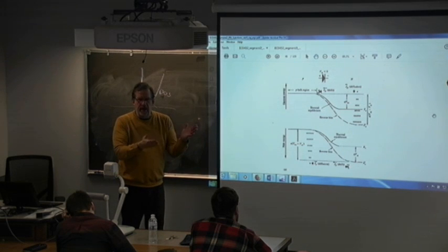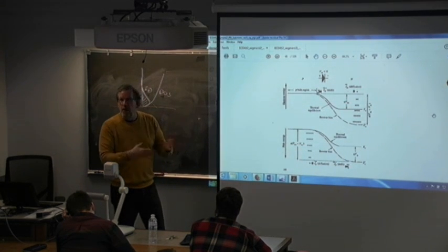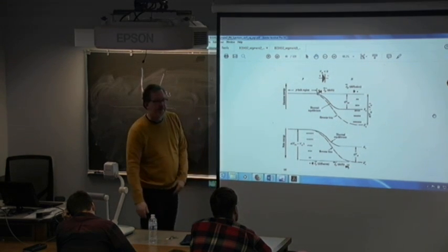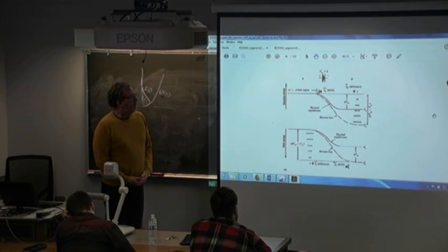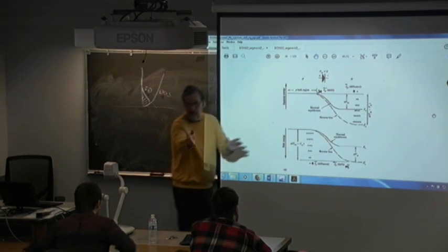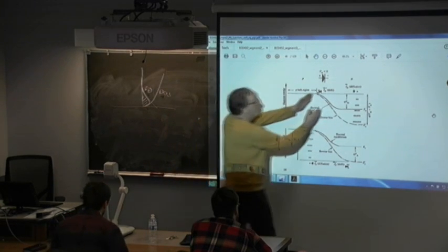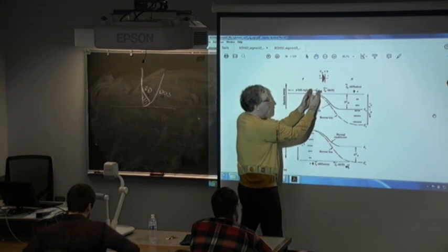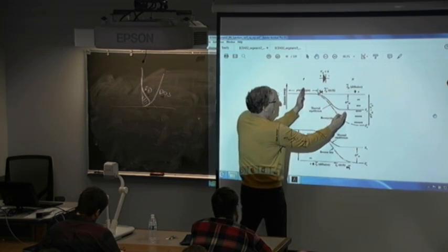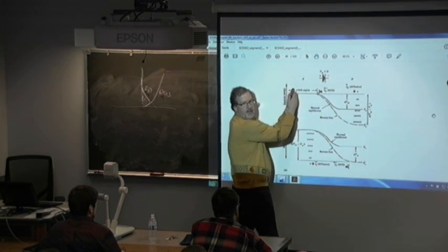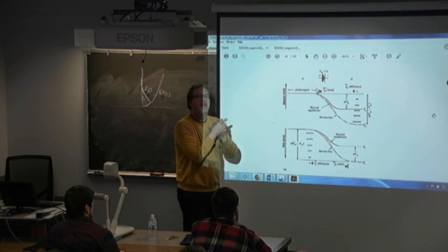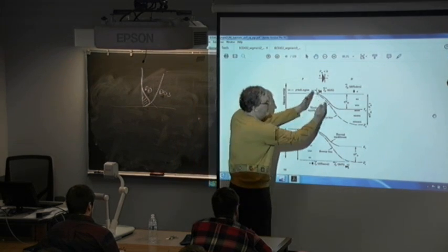It's like the adage of a tree falling in the forest, no one hears it. So it basically will disappear before it can get to the junction edge. So even though the depletion region is getting bigger, it doesn't contribute more to the current. Well, that's the deviation from ideality. Yes, exactly, you're getting ahead. If the depletion region widens and the diffusion length stays the same, then as it comes back here, it's within the depletion region and within the diffusion length criteria.